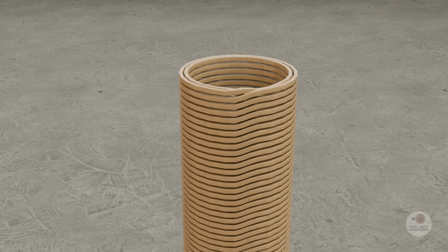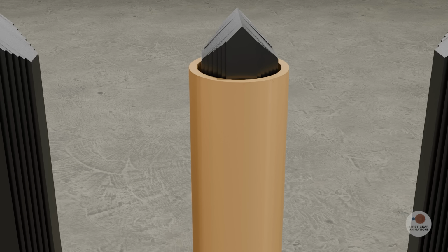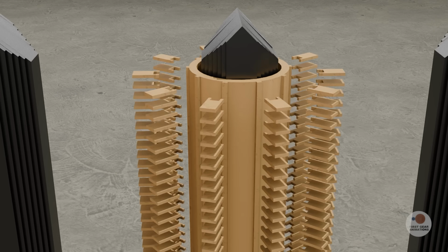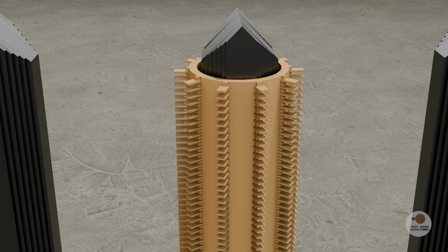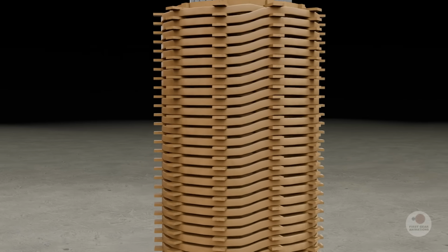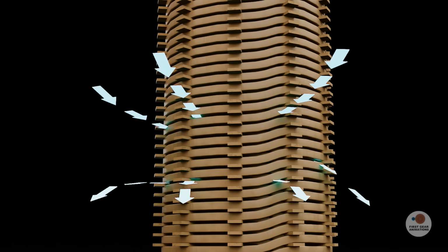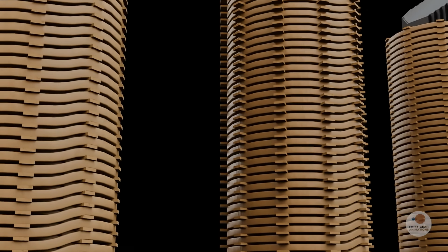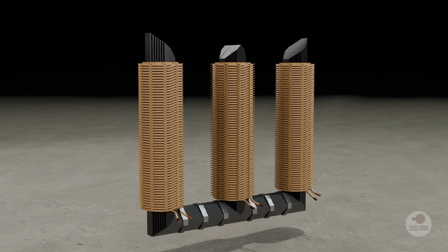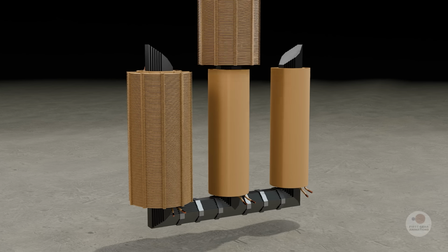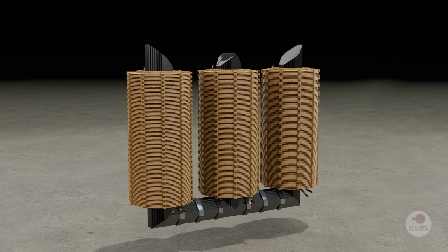To ensure these coils remain stationary under the immense mechanical stress of high voltage surges, engineers use high-strength pressboard axial spacers and radial spacers to hold the windings firmly in place while also serving as cooling channels, allowing dielectric oil to flow freely and carry heat away from the assembly. Once the low voltage winding is firmly secured, a thick layer of insulation is applied over it before the high voltage winding is placed on the outside.